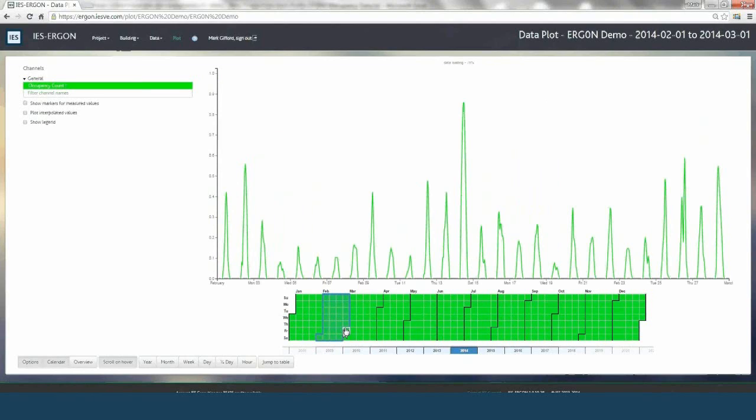You probably find if you're looking at BMS systems in particular that the data yield can be quite patchy, just due to maybe communication issues on site, whereas your metering infrastructure tends to be more robust. So if you're looking at main utility meters, chances are your utility company will have a good system in place, because that's what they're using for automatic billing. But the BMS is certainly a bit more patchy.